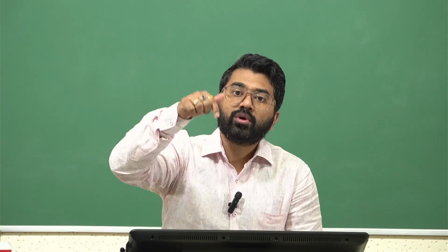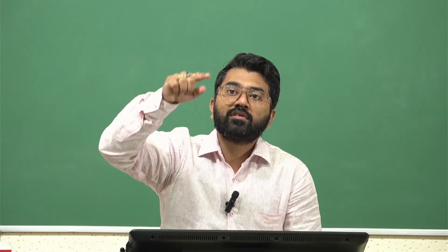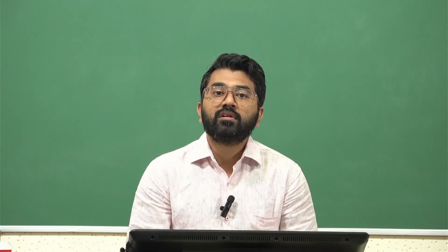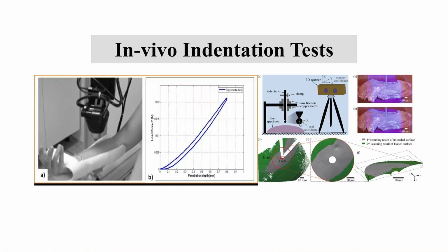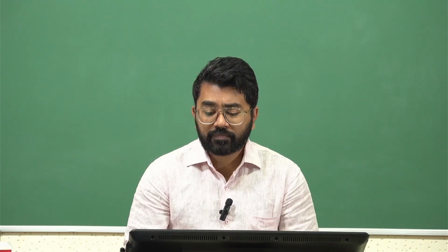Because that's how it is poking on the skin. If it is a flat surface versus a curved surface, it has a very different kind of load response, right? So as this is done, a 3D scanner scans the coordinate which is connected with this indenter. So it's a very high precision measurement which takes displacements in the order of less than a millimeter, and you're measuring forces much less than a Newton.